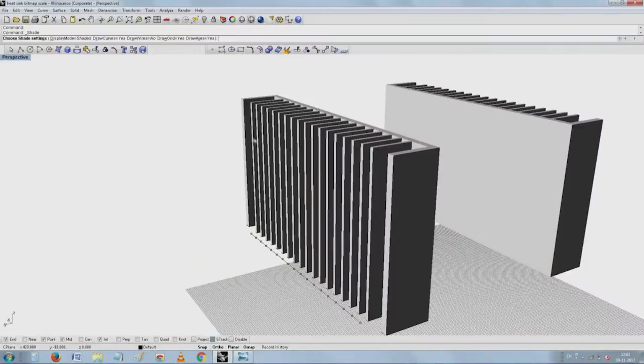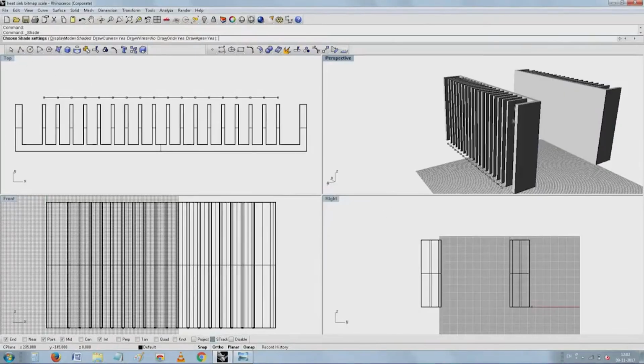Similarly, if you take the height, it goes in terms of U's. 1 U is 44.45 and so on, and then generally 3 U. Typically 3 U rack will be 132.5, and this is a good starting point for a rack with heat sinks in the vertical direction on the face back. Now, while this is one of the conditions, it is not the only way you can do it. It is very much possible for me